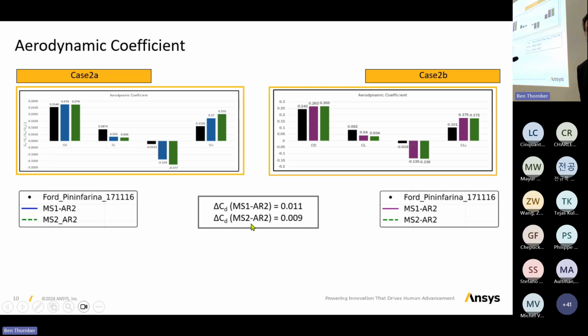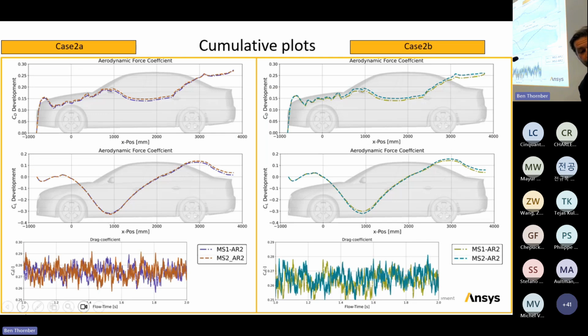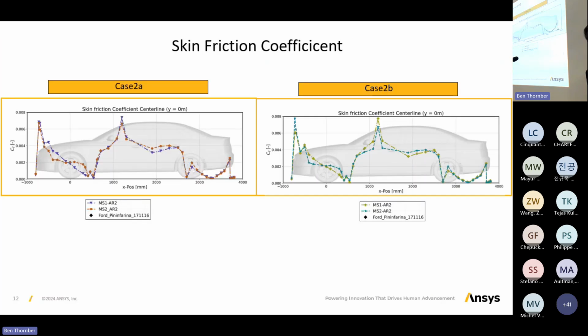The averaging times we used are a bit short. Probably we did 2 seconds overall run and 1 second of averaging. So as you can see, the spread is fairly large, and I don't know how accurate those delta values are. And again, I'll just race through those because really the message here is that mesh refinement for wall function LES didn't make any difference, and it's basically on every slide. Those are the CF values. There you can see a little bit of a difference.